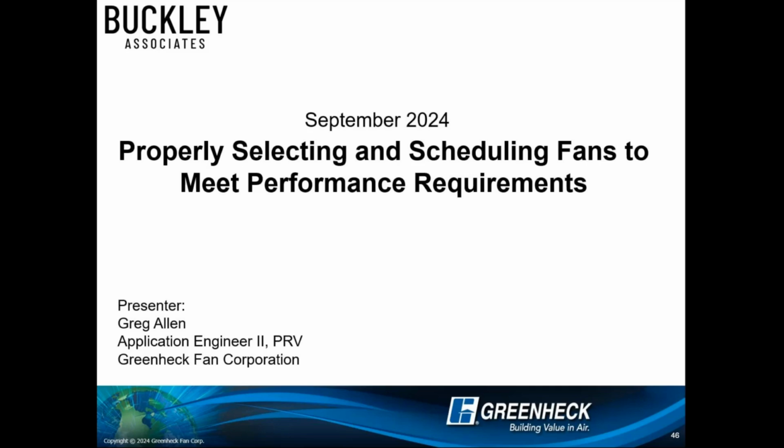I look back at all those fans that can do that, and I say, okay, you wanted a downblast or an upblast, it's a CUE. What RPM do I need to run where I intersect 1,200 CFM at 2 inches? So it's a combination of test data, fan laws help me get there, and then calculation. This fan that you picked at this size, 1,000 or 1,400, whatever it was, that's the RPM I need to move your air against that resistance.